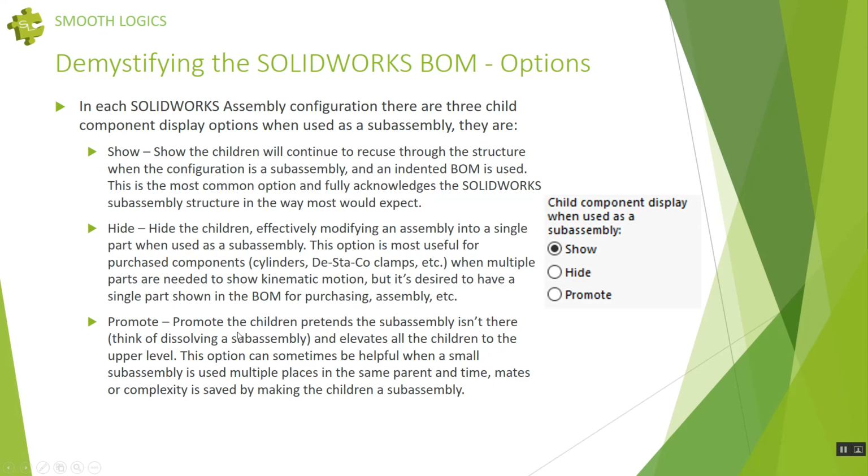So that's the hide, and then promote just does the inverse. Instead of hiding the children and pretending the assembly is a part, it hides the assembly and promotes the children up to the next level.